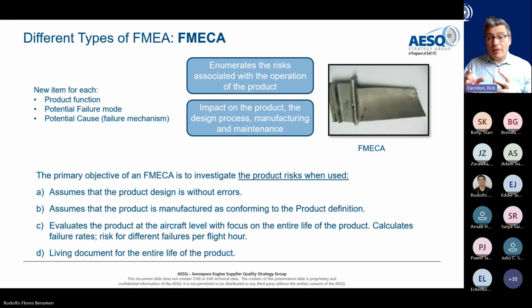It may have an impact on the processes that we've just talked about, DFMEA and PFMEA, but it's more that if it identifies a particular issue, it can feed back into those. Failure modes that have historically been seen in a FMECA could feed into a DFMEA, for example.